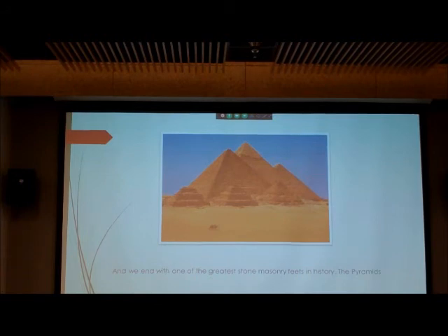You said they're using curtain walls, how do they utilize stone? I didn't look into it very deeply, but they basically just make panels and hang them up. Especially granite, your high end, they'll make anywhere from 1.5 to 2.5 inch panels, and they'll put them up. Limestone's the same way, maybe a little bit thicker. And they'll have inserts to attach it.